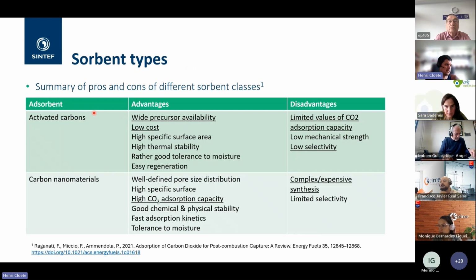So here's quite a nice table that I found in a review paper that's cited here. I think if anybody wants a quick overview of adsorption-based CO2 capture, this is quite a nice paper. I won't go into the details here, but I just quickly want to give an overview of the different types of solvents out there and some of the key features or benefits of the different ones. So one category is activated carbons, whose main advantage is there's a lot of source materials for that, and they're low cost and widely available. But the downside is that they can have limited CO2 capture capacities and low selectivity to CO2.